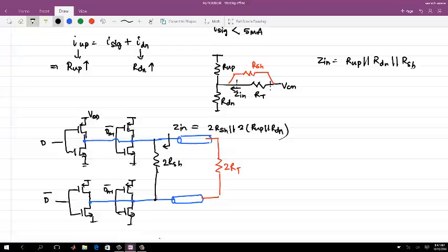Yeah, that RSH will consume current. The whole thing is whether the total current is going to be more or less. The thought is that you reduce the total current by increasing the impedance, and then you have the channel termination, and whatever current is drawn is split into RSH and RT, so the total current is still lesser. Our goal is also to have a current which is constant. Right now we are looking for a current which is lesser and also constant, because if you do not have a constant current, that will cause more supply